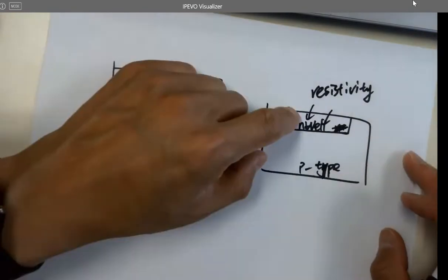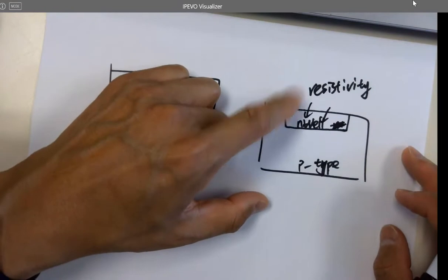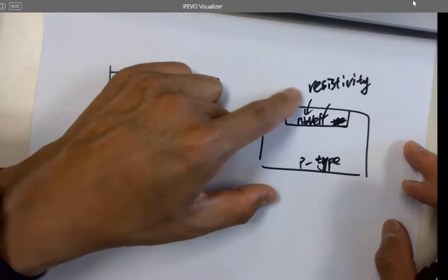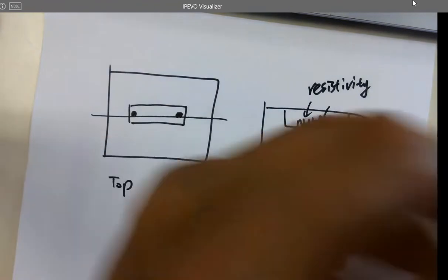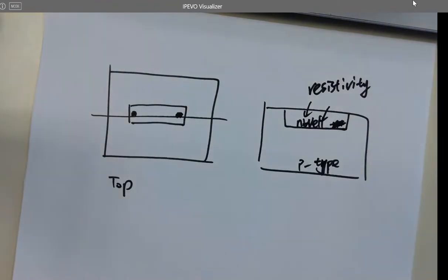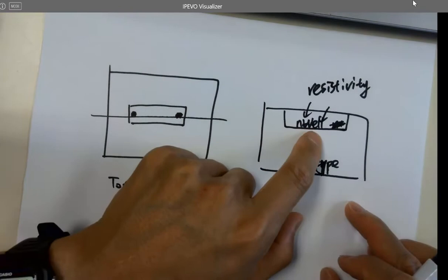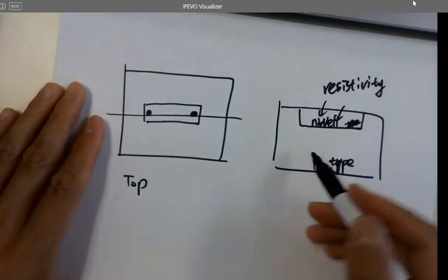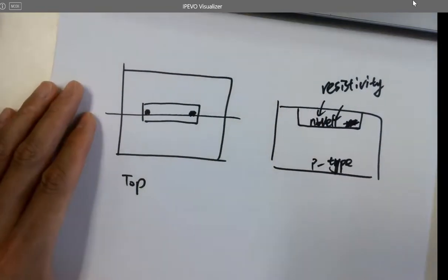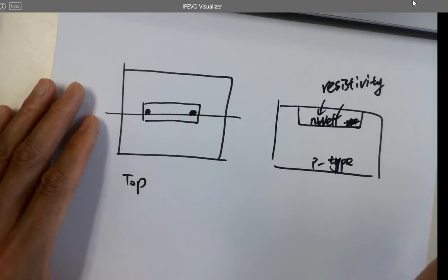But this is not the only material that can be used as a resistor. The polysilicon on the top layer here is the same as a gate, right? So if you make a super long gate, you get a resistor. But N-well is being used as a resistor as well. And what you need to know is that this is a 3D structure. You can imagine, right? It has width, length, and thickness.